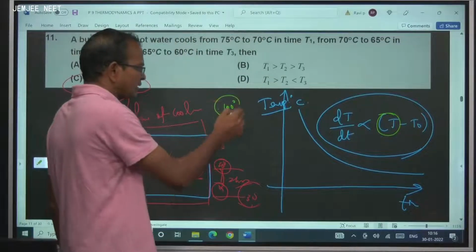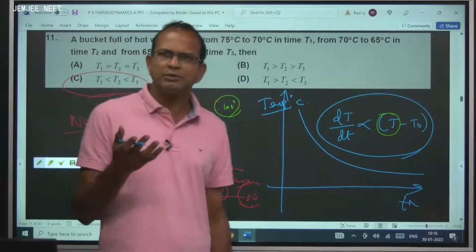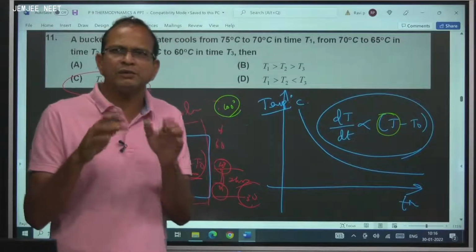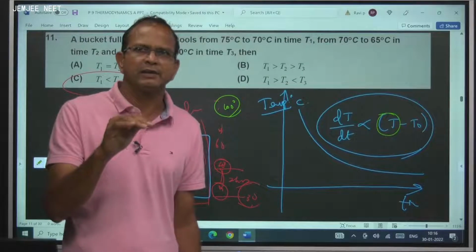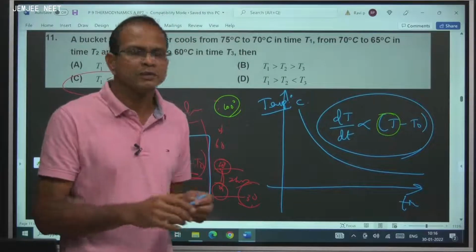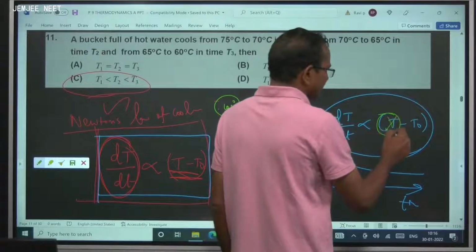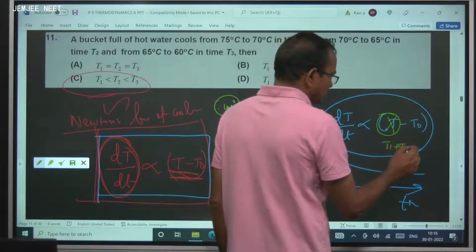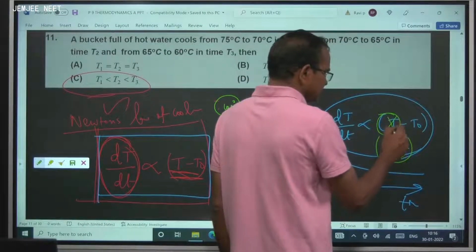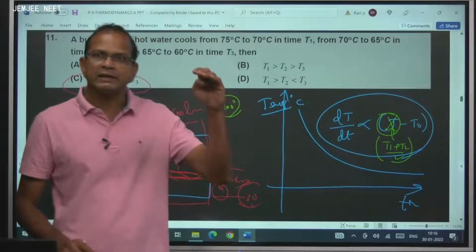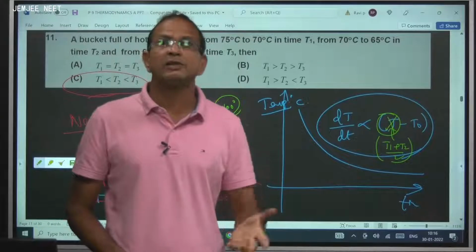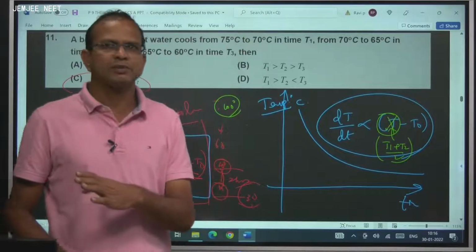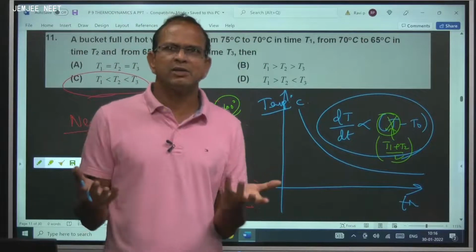I talked about 100 degrees Celsius with you, but can I tell you that the coffee is always at 100? No, it started at 100, 99, 98, it came to 90. So here T is always replaced by (T1 plus T2) by 2. What is T1? 100 degree. What is T2? 90 degree, by 2. So you have to always take the average temperature of the range. Range need not be always 10 as I said.